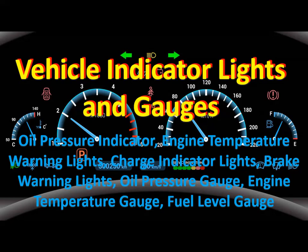When you understand normal indicator light and gauge operation, you are able to diagnose problems in these circuits. Technicians must be able to quickly and accurately diagnose whether the defect is in the indicator light or gauge itself or in the system that the indicator light or gauge is monitoring.